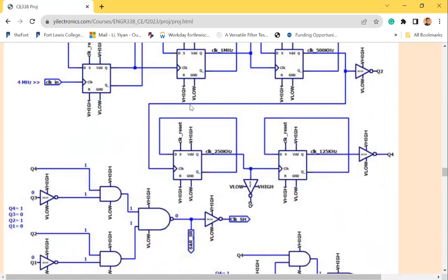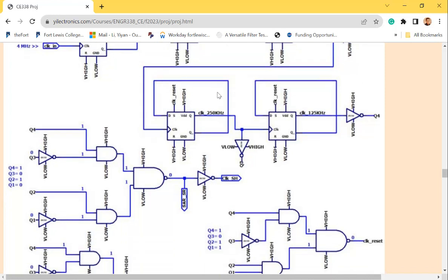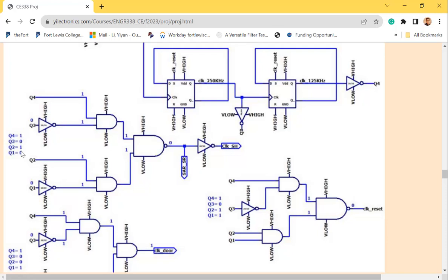because this original counter cannot count until 10, it just keeps counting upwards until 1111, right? That's the maximum number, and then it's gonna reset because it doesn't have another register following. So it doesn't have a carry out. It just resets to all zeros after 1111, all right? But we don't want to count until 1111, which is too big. We just want to stop at 10, right? How do we make that happen?